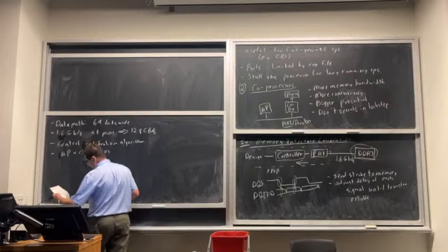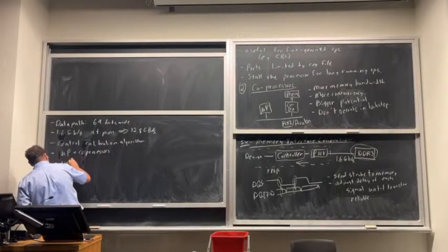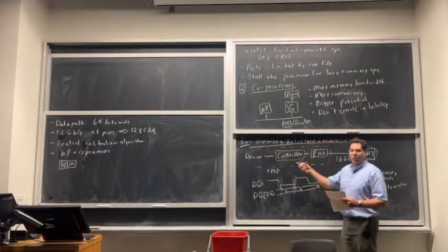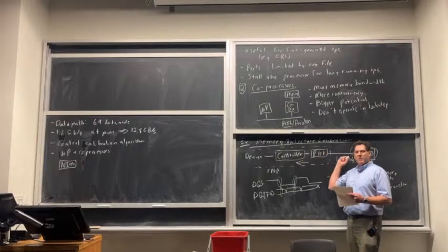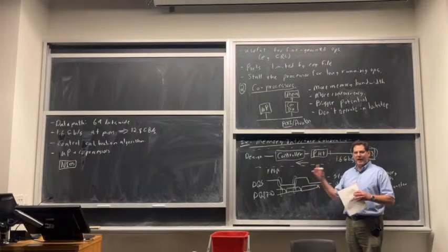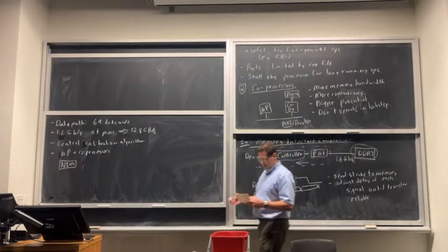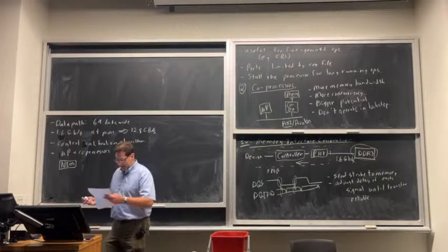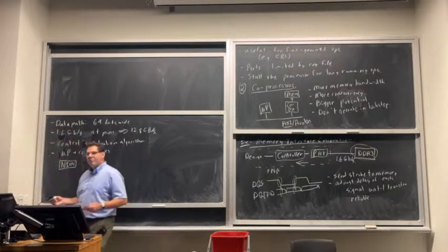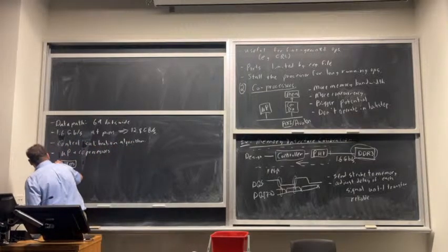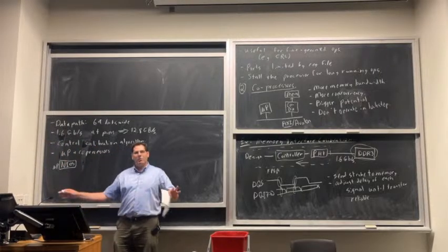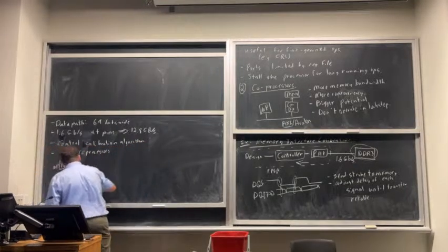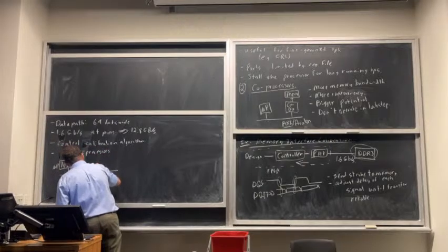Okay, so what we did is took a soft processor, because you could have like 6 or 8 of these memory controllers in an FPGA design. Like you can actually have a lot of different DDR chips or other related I/O standards on the board. So you might need a lot of these. So not every FPGA has hard processors at all, and then they don't have enough, and maybe not in the right spot. So we use a Nios, which is a soft processor, and we use the small version of it, so it doesn't take that much area, but we can now put it down anywhere we want, right? If you need 8 interfaces, you'll get 8 of these. That speaks over a standard bus, which in this case was Avalon, but could be AXI.